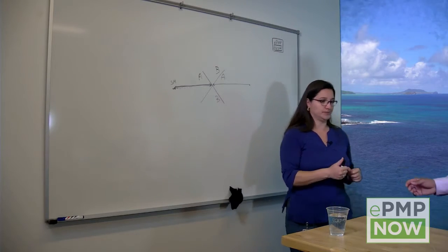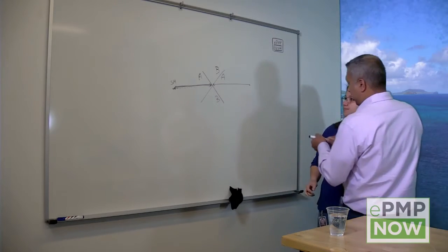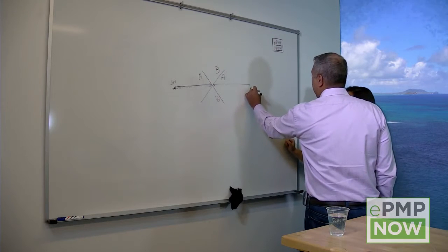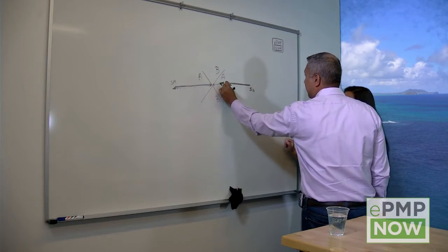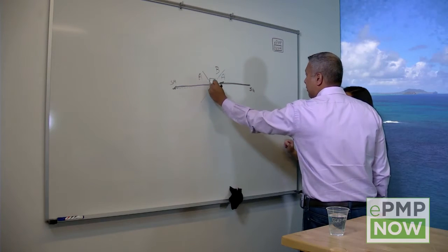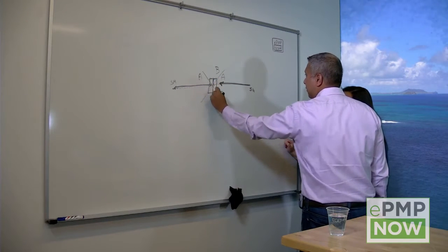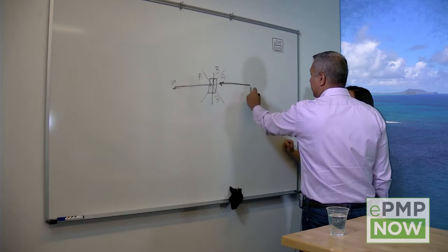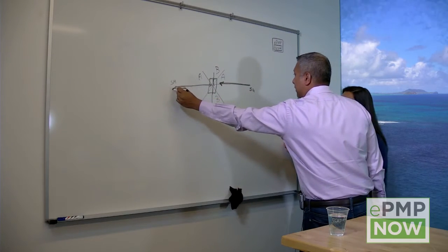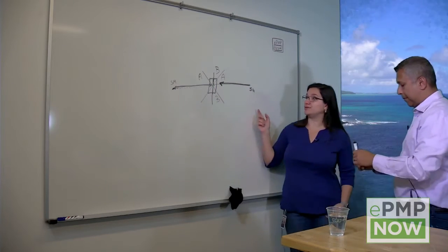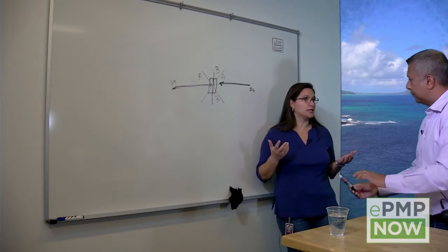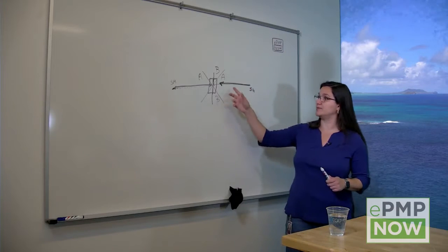So what you're essentially saying is, if I may draw this a little bit, this is a subscriber, and this is in the uplink direction. Energy from this subscriber is going towards that. You have 2 antennas here, and the front to back here causing this SM's energy to be heard by this subscriber as well as the back of that AP. Correct. And in the uplink direction, things are a little bit more randomized because, of course, both sectors will be scheduled.